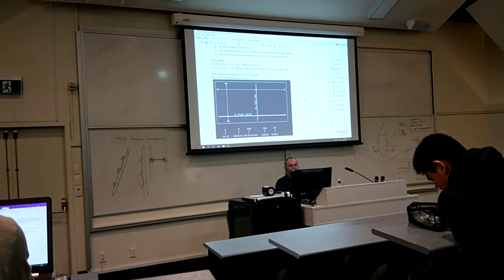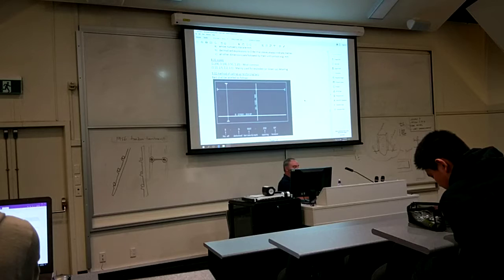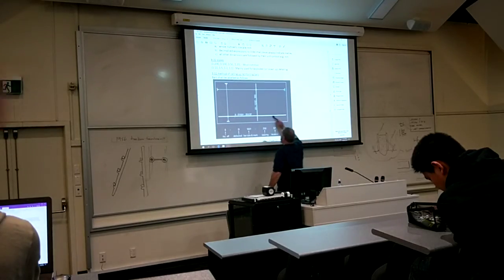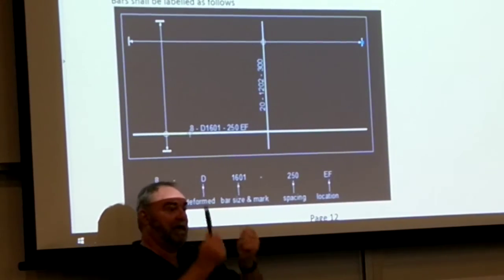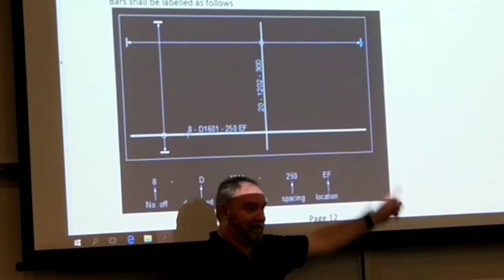So here we have a typical way of calling up reinforcing bars. And we're going to get into more examples of this further down the line. I'm going to make an AutoCAD example available to you to have a look at, which will have the way of calling up the bars, etc. And as you can see by this example here, the 8 stands for the number of bars, so you need to calculate that. So, and the bar itself is this one here. Now it has a flat edge, so that means it doesn't bend, go up or down, it's just a straight bar, right?